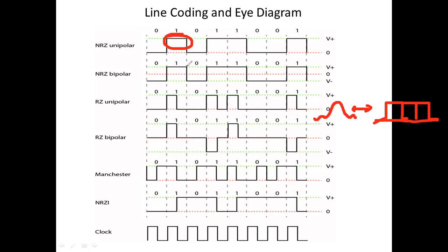Yes, they look fine in the time domain, but when there are lots and lots of codes, and when you try to modulate, then send it over the bandwidth, then you want to demodulate, you do not want any issues, then maybe sending these rectangular boxes is not a good idea. You will go for these kinds of pulses where there is a sinc and there is something called a raised cosine pulse. Okay. So assuming that you happen to know a little bit of that, now let me continue.